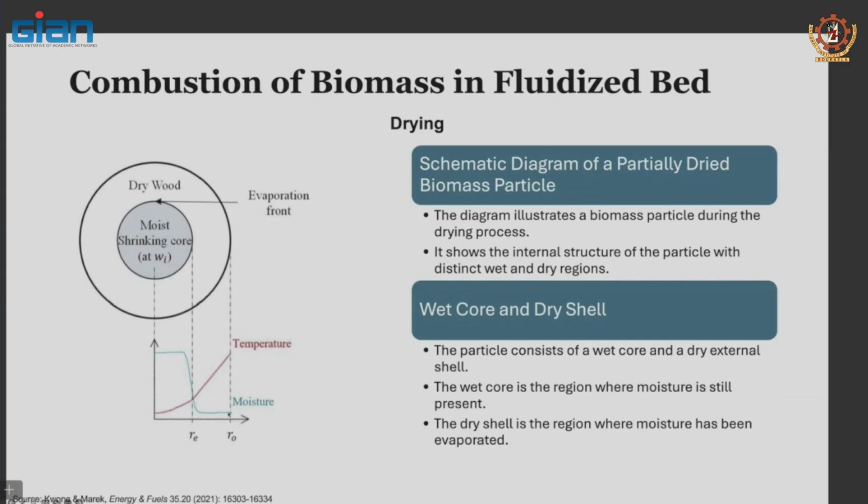you reach a point where you're no longer able to remove the surface moisture because the rest is diffusion controlled. When it's diffusion controlled, it is independent of temperature, as you can see. Regardless of how much you increase temperature, it flattens out. So this is the point that you need to model. This is why we're trying to model. This is the point that you need to determine, at which point you no longer need to dry it. Leave it because you have removed this part.